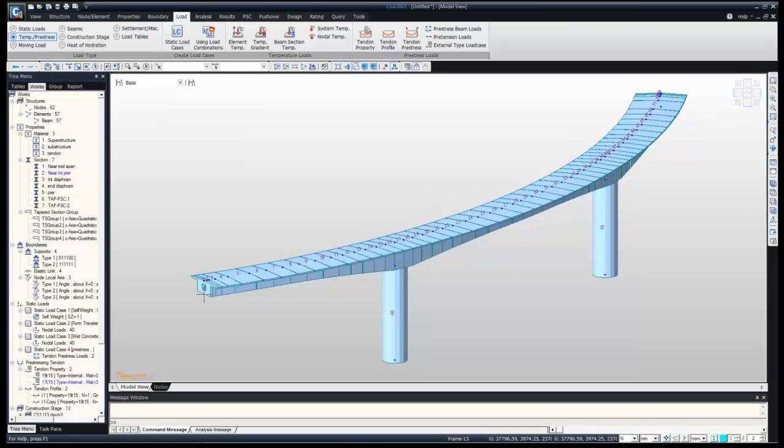So our pre-stressing has been done: first tendon property, tendon profile, tendon pre-stress. As it's going to take much time for inputting 72 tendons, I'm just showing how we can input just the 2 tendons, and in the same way we can go for the other 70 tendons.